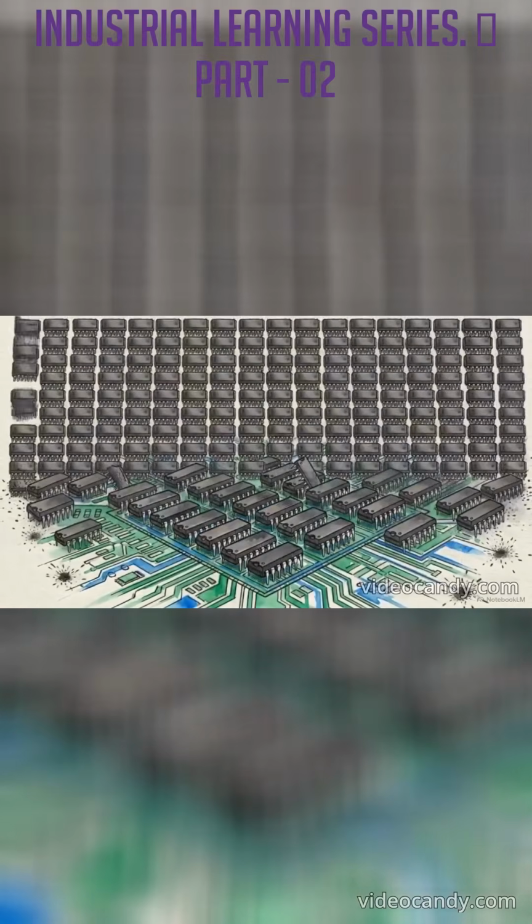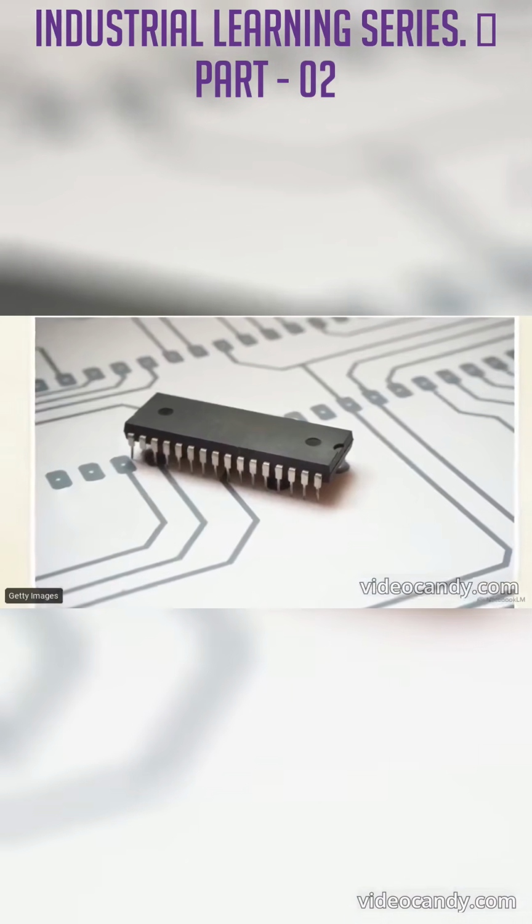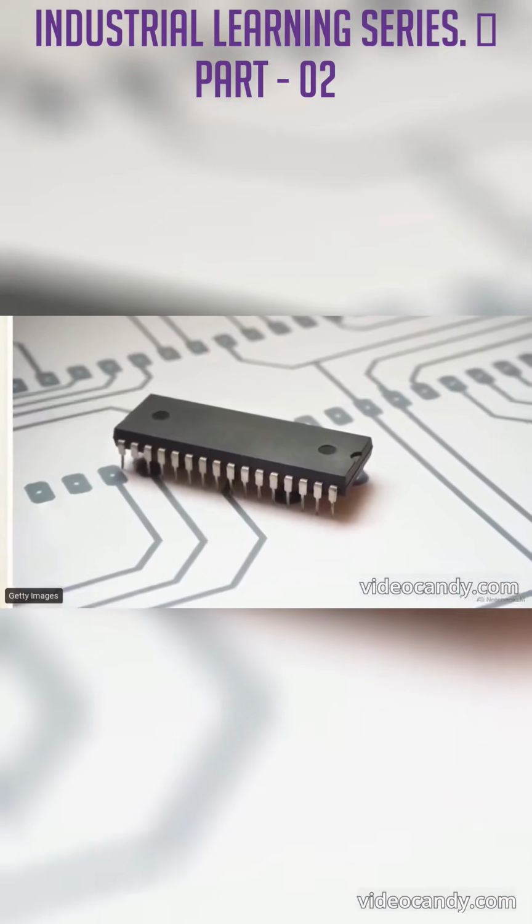They are called universal because with enough NAND or NOR gates wired together, you can replicate every single basic logic function and Boolean expression possible. This creates a massive engineering advantage. Standardizing hardware to universal gates drastically reduces circuit complexity and lowers manufacturing costs. Rather than designing bespoke chips for every distinct mathematical operation, a fabrication plant can just stamp out millions of identical NAND gates.